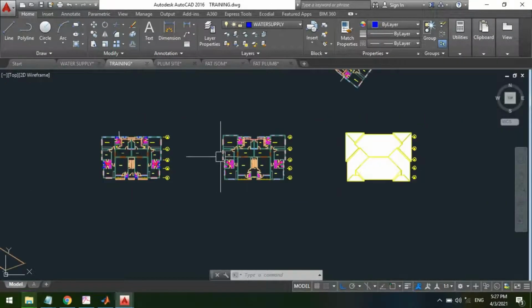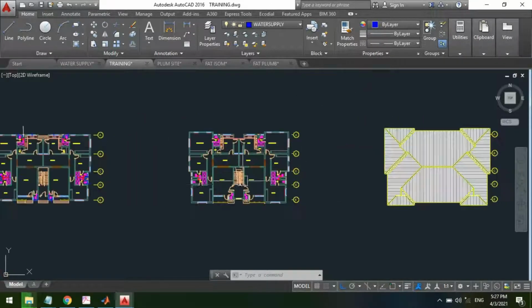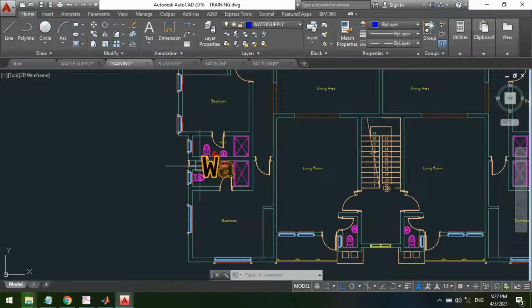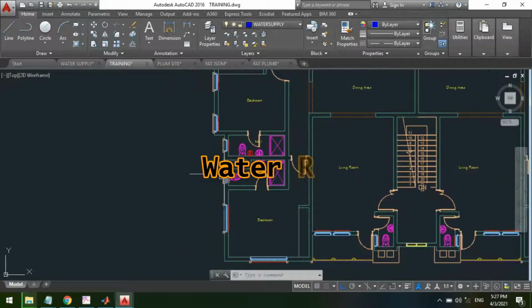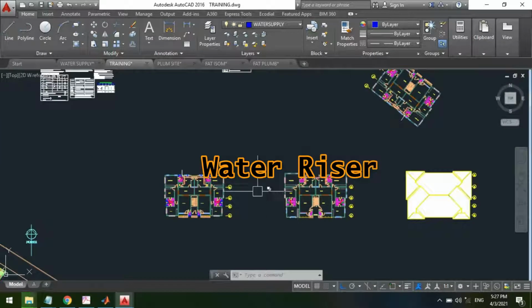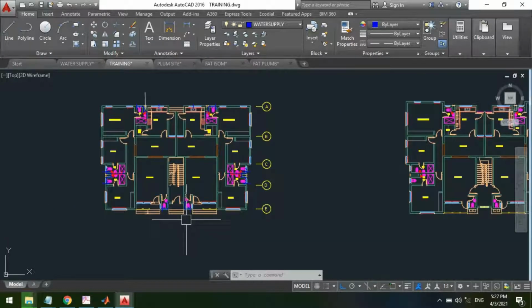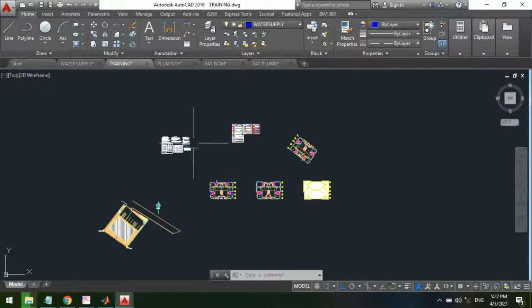However, if we have suspended floors, either first floor, second floor, third floors, and in some cases up to 10th, 30th floors, the major concern in this instance is the riser. And as I've explained, the riser is the pipe that brings the water main from the ground floor if you are using ground floor distribution, or from the roof if you are using roof distribution.